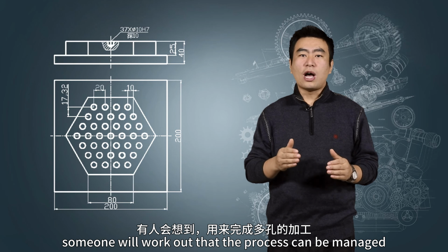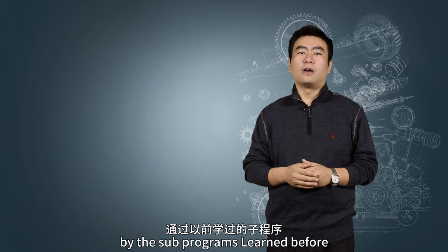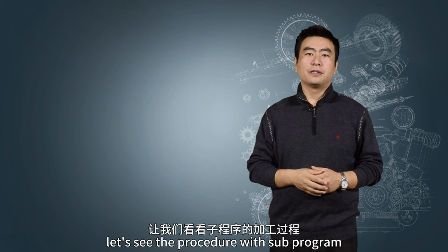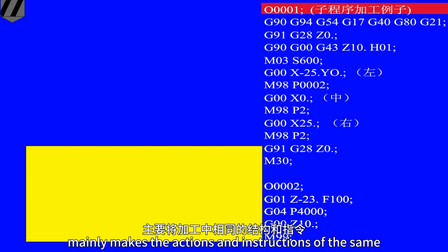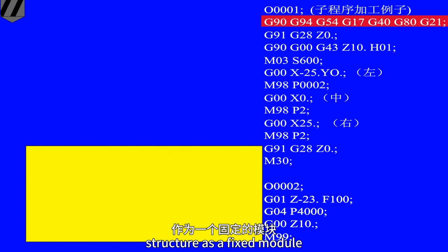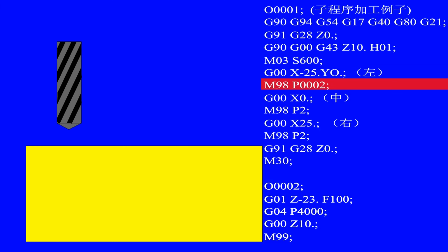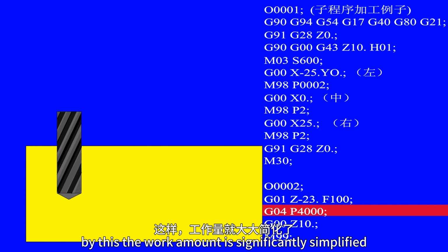Certainly, maybe someone will work out that the process can be managed by the sub-programs learned before. It's really awesome. Let's see the procedure with sub-program. The processing with sub-program mainly makes the actions and instructions of the same structure a fixed module. Now let's write a sub-program in the main program. First, we need to locate the different holes, and then we use the sub-program to finish the actions concerning processing the holes. By this, the workload is significantly simplified.